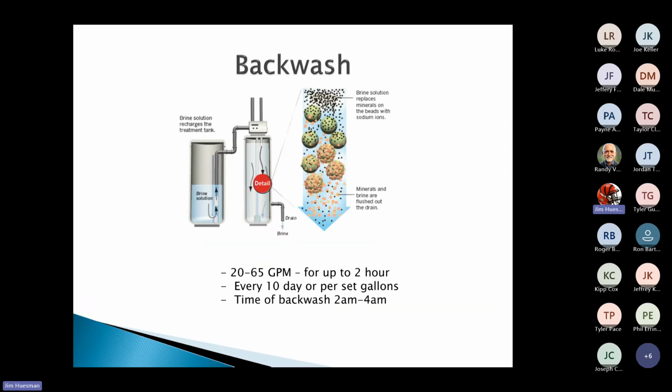So I'm doing that backwash, and the reason I put this up there, it's kind of a dumb picture. It actually looks like a water heater a little bit, but I put this up there because, when we're using a water softener and we go through the regeneration period, we need to make sure that drain is going to handle it. It's going to regen for about 2 hours, and you can dump anywhere between 20 and 60 gallons a minute. We may be on hours, times or days. It's all based on how we set it. But remember, if you just throw that regen line into a floor drain that maybe works, maybe doesn't, you'll be looking at a lot of water on the project. So make sure that drain is working. Because at 2 in the morning, the last call you want is, hey, my building's flooding out.